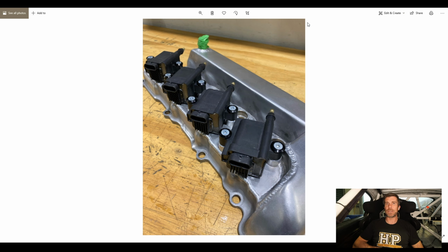There really is only one mounting hole that could be used to pick up for the coil mounting plate. And particularly in a race application, the physical aspects of removing the coils to remove and replace spark plugs or even check the plugs was a real pain. We couldn't do it quickly, and just in my opinion, not something that was a smart option for a race application. So what we've done is we've gone to a set of the fairly well-proven IGN-1A coils. They're cheap, they're cost-effective, they do a good job, and they put out high spark energy, also really easy to source replacements. Mounting the coils though, I didn't want an ugly mount hanging out over the fuel rail or the plenum chamber, and we wanted something nice and reliable.